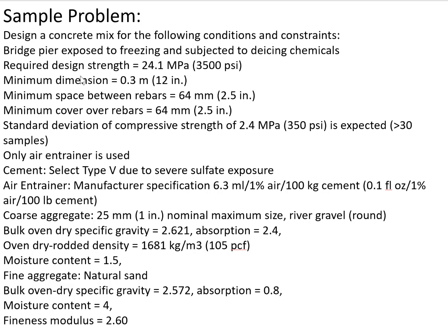The required design strength, minimum dimension, minimum space between rebars, and minimum cover over rebars are provided to you. And the standard deviation of compressive strength is 2.4 MPa. It's obtained based on experiments performed on more than 30 samples. And only air entrainer is used in the mix design, no other admixtures. For cement, we selected type 5 due to severe sulfate exposure.